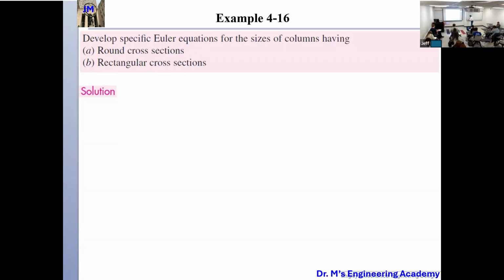If you plug in, this gives us the square root of B H cubed over 12 divided by B H, which is H squared divided by 12. So this gives us 1 over the square root of 12 multiplied by H. So this is our K. You can just substitute this K into that equation, and also A into this equation, and you will have the B.